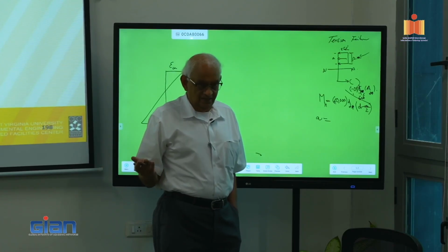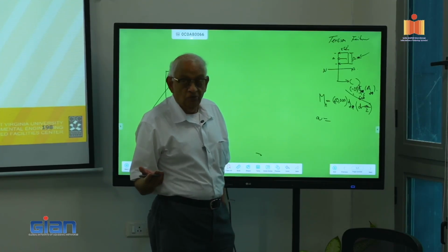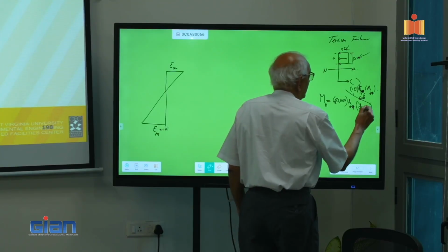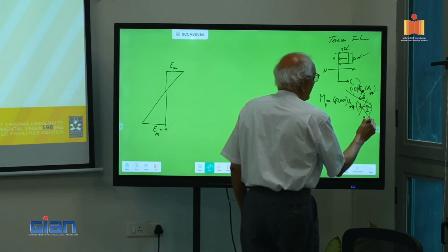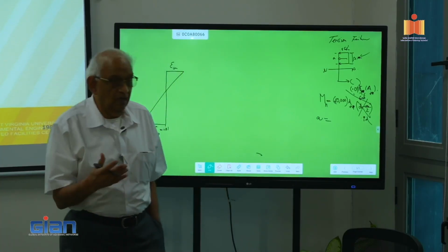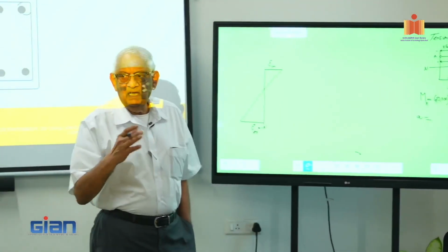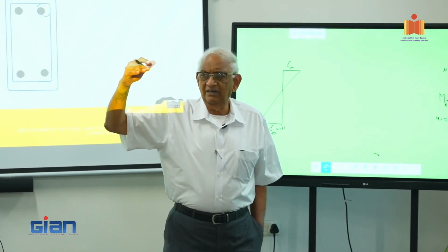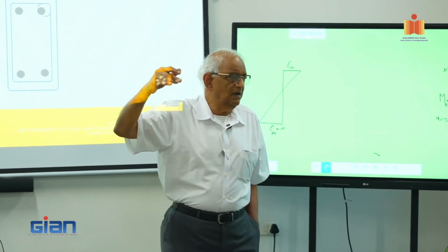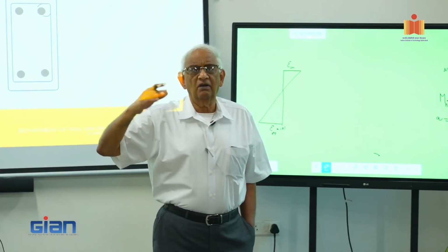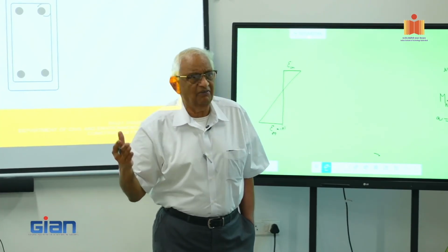That is the advantage. You know what a lot of people do? A lot of people would simply say, I have an approximate value, because we have many other factors of safety. It doesn't matter whether d minus a over 2 is 0.9d or 0.85d; it's going to hover around that number anyway.